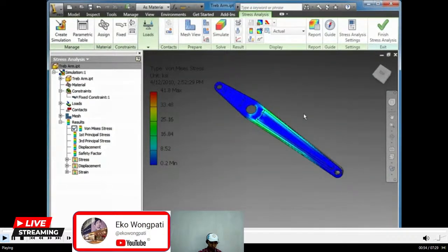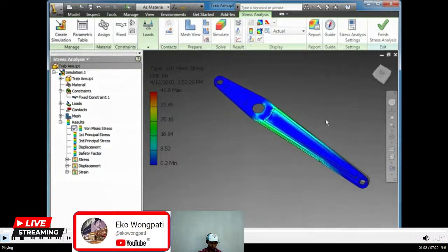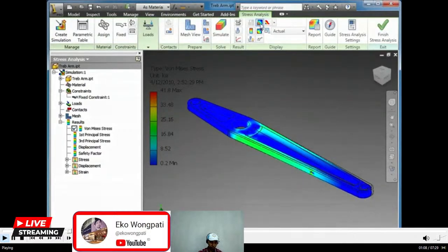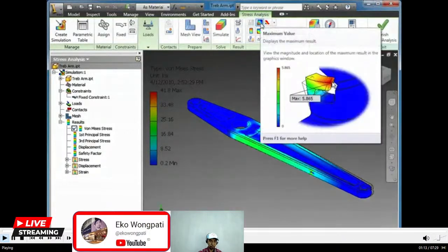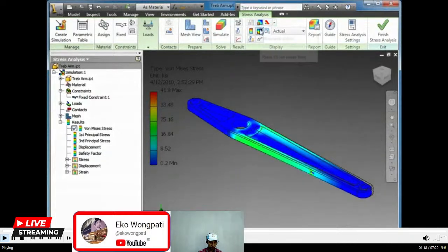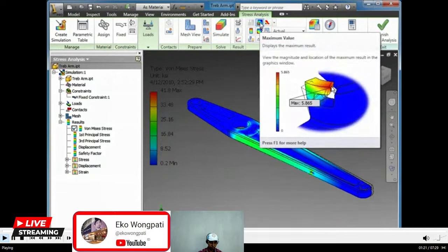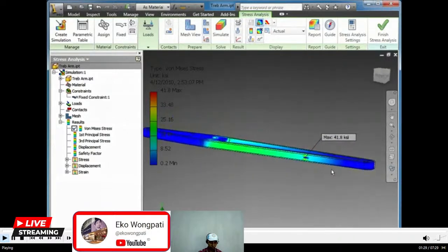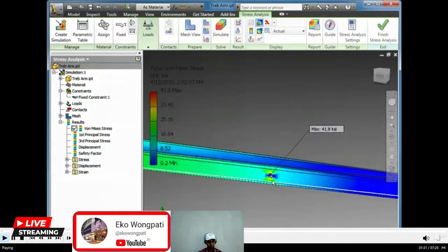It comes in handy, if it's only a minor change, to get the scaling, so you can see where things are taking place. Some nice things to call out. Here we're looking at the von Mises stress. On the toolbar, right now because I'm in only a 1024 by 768, I don't see the labels, but in a larger resolution you get labels for all of these buttons. There are toggles here where, if we want to quickly see where the maximum stress is, we can click that toggle, and it puts a pointer right to where the maximum stress is here.